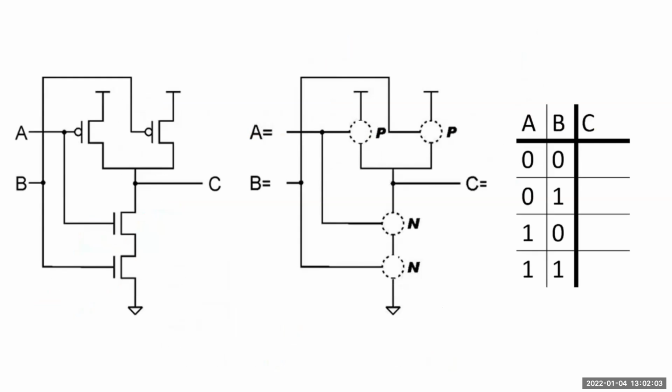When we build more complex digital logic circuits, it becomes important to notice there's another part of what makes these complementary. Down here, NMOS transistors are connected in series. That means the output of one is connected to the terminal of the other.